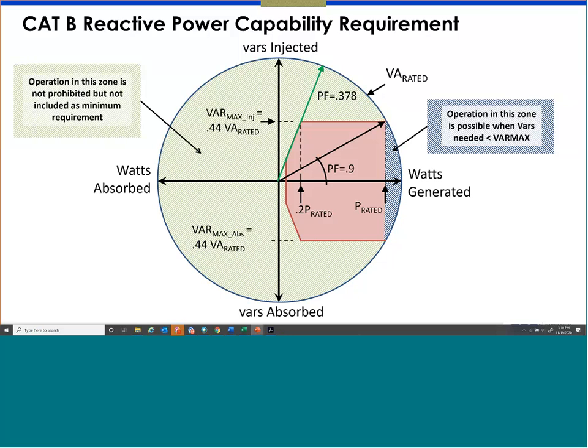In that case, one major change I can think of is this: if the control electronics of the inverter are designed to be powered from the DC side, like in the early morning the panel starts generating DC power, and that powers the control electronics, which do all the switching, monitoring, everything, then that will not work during nighttime. If that's the scenario, then the modification will be something significant. Either they have to put in a UPS or a rectifier to get power from the grid, control electronics power I'm talking about, to keep the electronics running so that the plant can generate power.